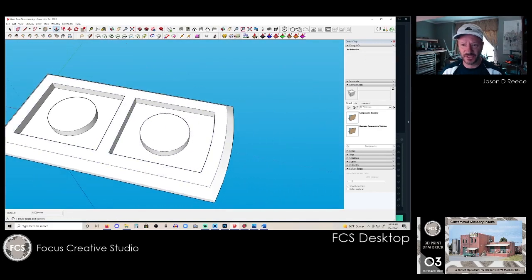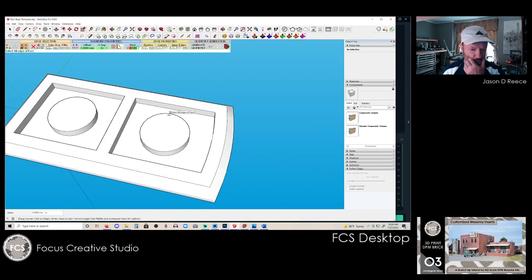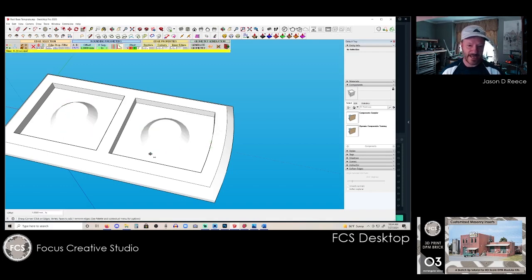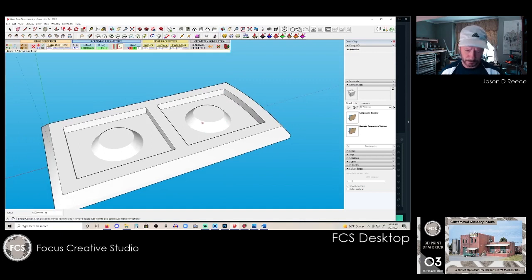I'm going to go ahead and bevel these as well. It cleans things up when I'm trying to place supports and prevent islands. So we know that this is actually 1 millimeter thick, so we'll keep this at 1. And if I just select inside that, it will grab that whole piece. Now those pads are part of the model.